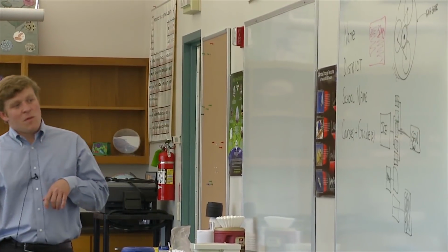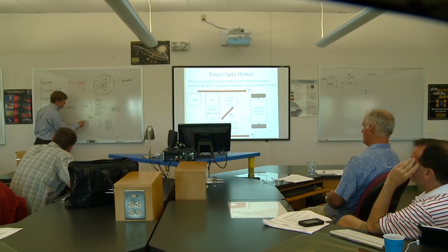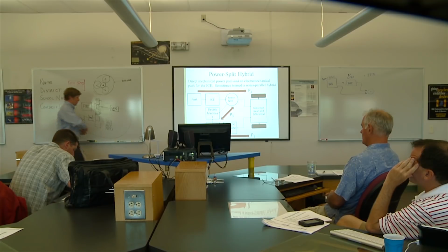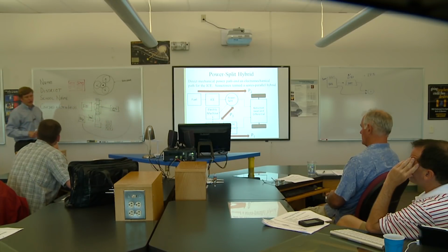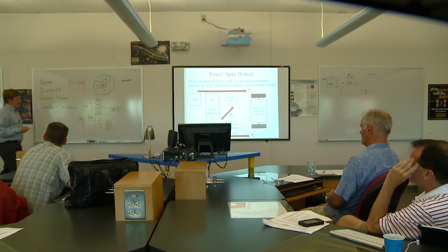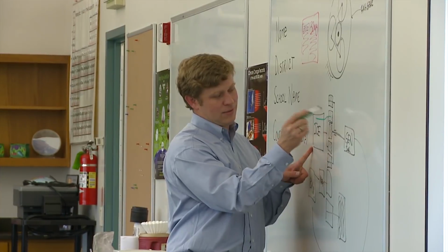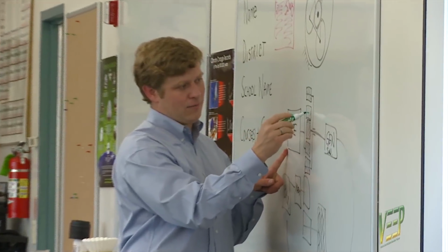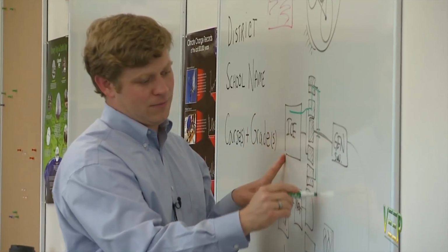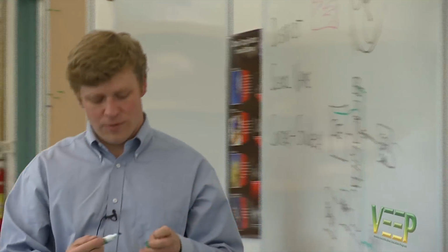It's a little weird to think about, but the global idea here is that both motor and generator are connected electrically to a battery. And now we can look at this diagram and put connections on it that represent series and parallel paths. If you want to do a parallel path, you take the engine and drive power from the engine into this gear set right here, and then it will go out through this output gear set, out through the ring gear into the wheels.